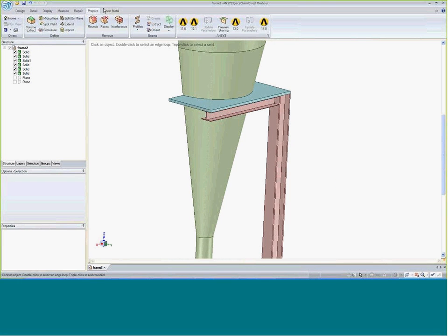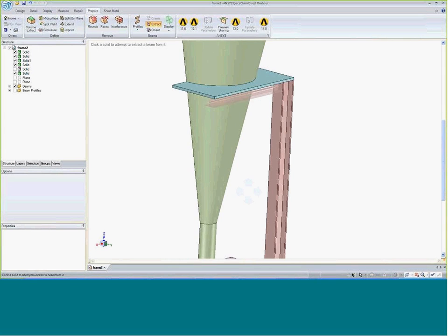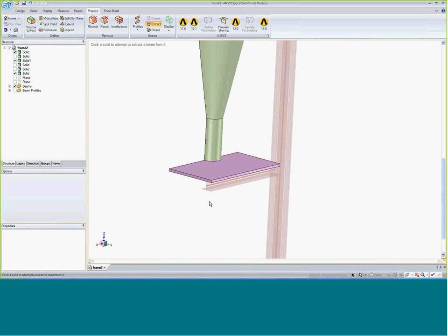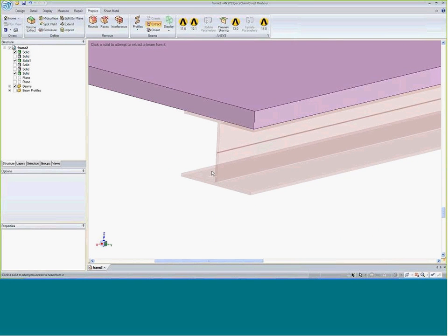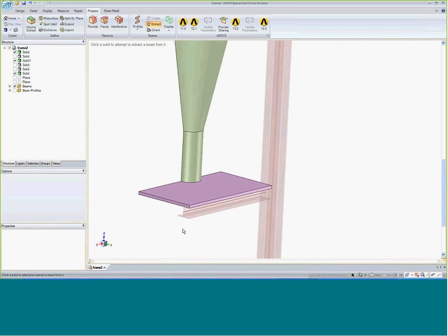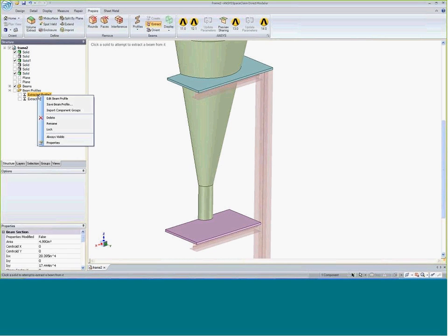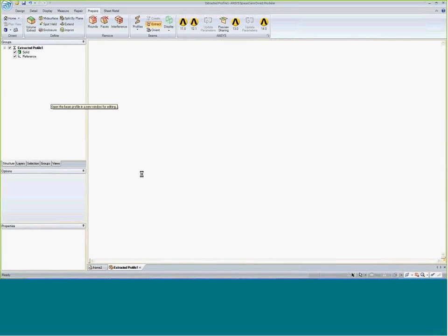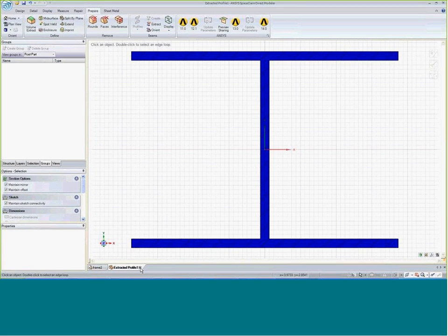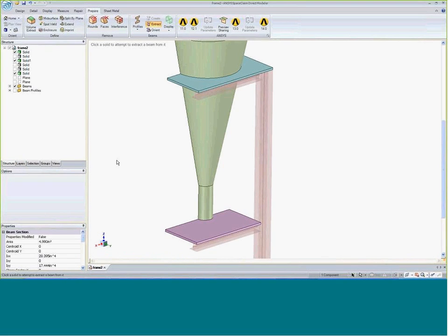So using it takes the body and decomposes it down to a beam. And if you zoom in, you can see the beam that's represented and then also the cross-section that comes along with it and its orientation. So this makes it very quick and easy to convert solids into beams. And this could also have some non-regular shape, it just takes the average of it. And you can always look at the cross-sections if you wanted to and modify them if you'd like. Those are all there. So that's good.